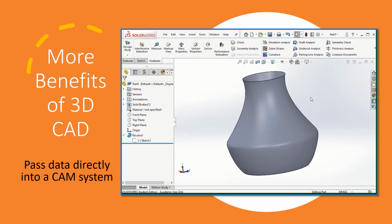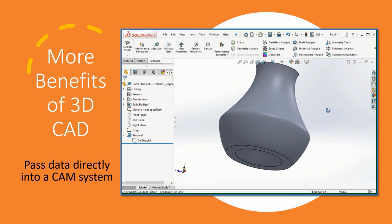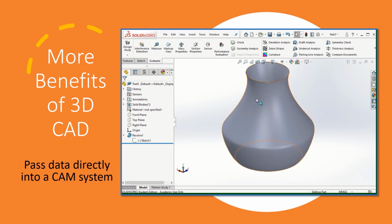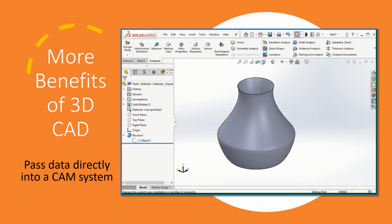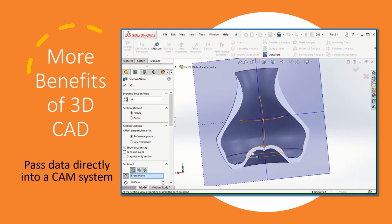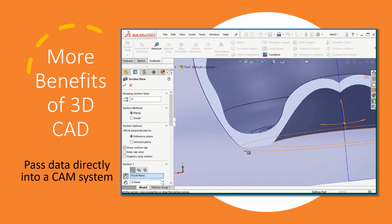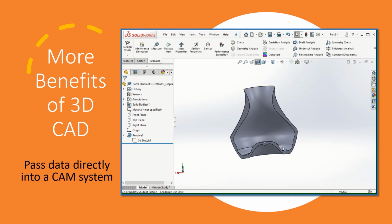Another benefit of CAD is that we can pass CAD data straight into a CAM system. What I've done here is created a little vase that I'm going to 3D print, and I will show you how to take this out of SolidWorks, out of our CAD system, and put it into the CAM system for the 3D printer. So all I've done here is to create a revolve, and I'll just cross hatch it for you. There we go. So I created a revolve, created half a section, revolved it around the center line, and put a little flat on the bottom here, and that flat will enable me to put it on the 3D printer plane nice and easily.